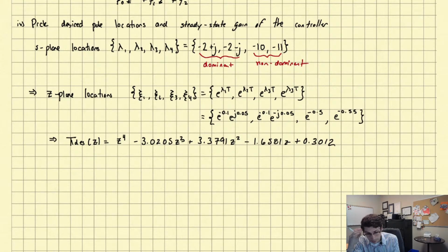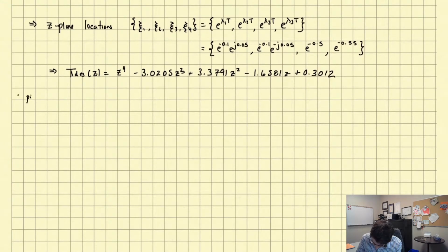Okay, so we have to pick this delta parameter. This delta parameter is our last equation when we're doing practical step tracking. So delta, pick this delta value greater than or equal to R naught over ESS max, which is 1 over the 5% maximum tracking error, minus 1, and this is equal to 19 in this case. Okay, this was given in the specs. So let's use equality. I mean, I could pick a bigger value, but let's just use equality. Let's use delta equal to 19. It's a design choice.